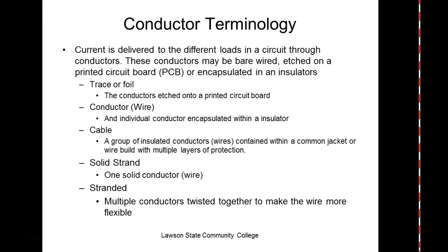So what we do on solid, a lot of times to splice it, we just twist wires together and put a wire nut on it. Stranded, we have to make sure, because if you lose one strand, you change the gauge of the wire. So we'll look at how many strands of the wire we can legally cut. If you've got a solid wire, how many can you cut? None. You can't cut one because you change the ampacity of the wire. The more strands you have, you can nick them a little bit, but you've got to be really careful.